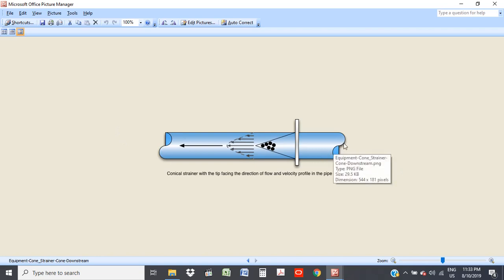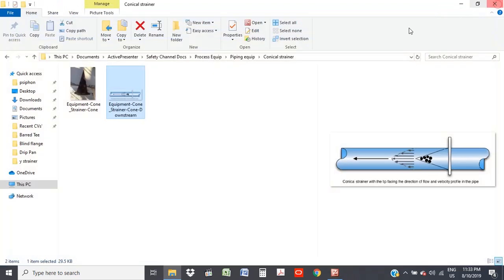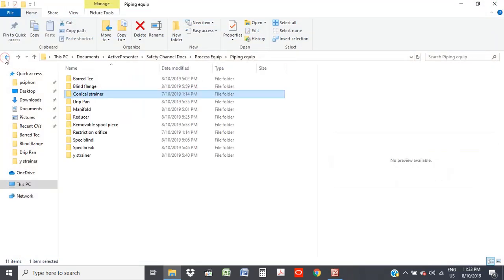All it does is, it's like a sieve, and it catches all the impurities in the fluid, and stops them from going to whatever equipment, like a filter. And periodically we bring out the conical strainer and clean it. So sometimes, depending on the scenario, you might need a conical strainer, or you might need a Y strainer.